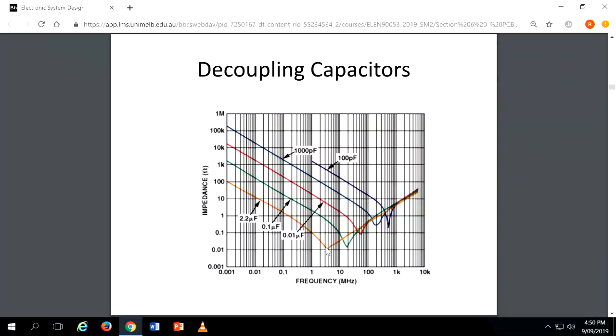So then we should know each capacitor, what is this point, because we have to select that one for your IC. Obviously you can put another one, but then the effect is less. For 3 megahertz maybe I can use the green one, still it will short it, but because the impedance is this much, it will not short properly. So this is the best. So this is an example.